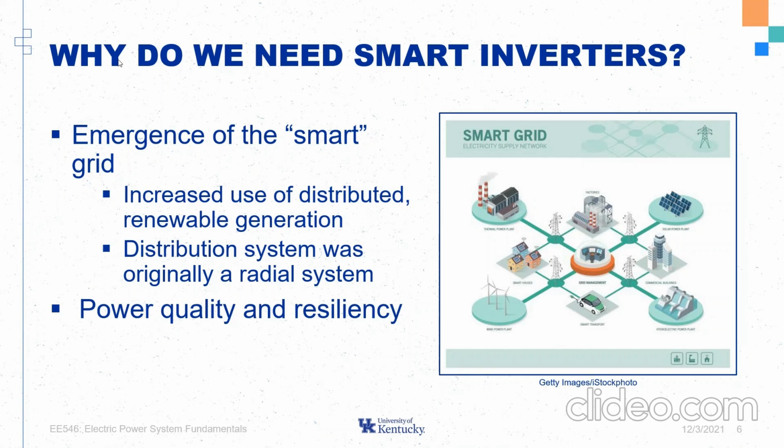Traditional electromechanical generation methods implement load frequency controllers to regulate their power output. However, since generation sources like solar and wind do not produce electricity electromechanically, a different control scheme is needed to avoid fluctuations in the voltage and frequency of the power in the grid. This is where the added capabilities of the smart inverter come into play. The smart inverter takes on the same role as the load frequency controller.